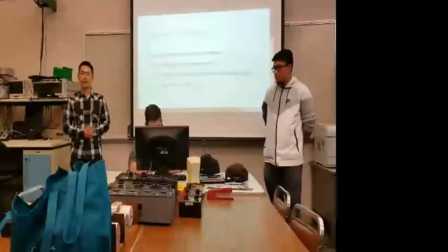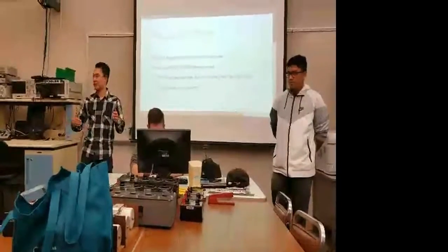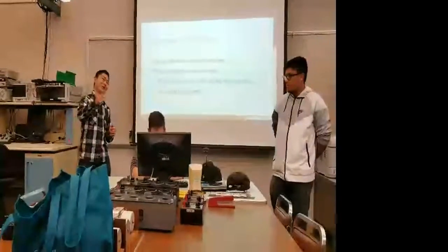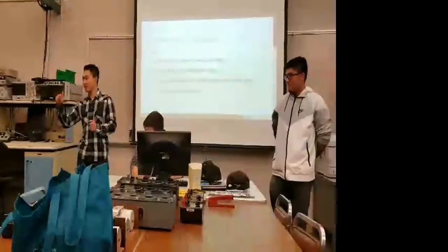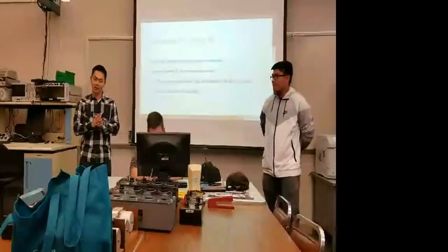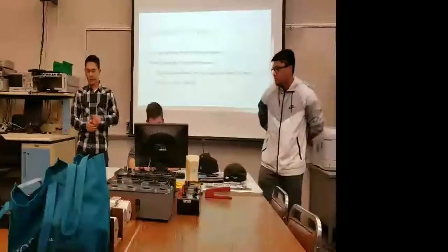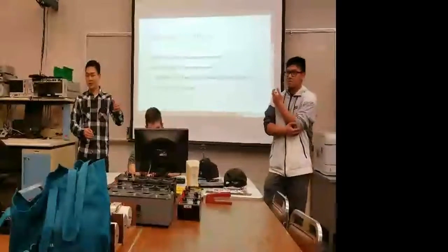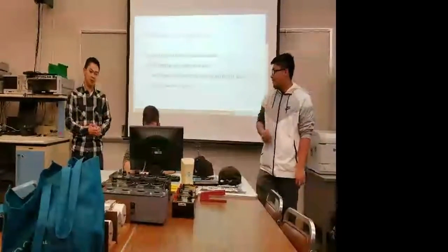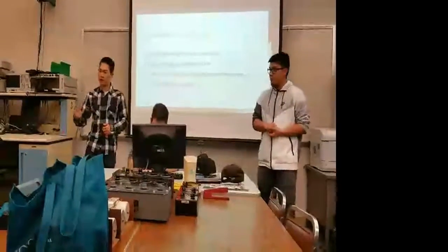The component that gave us the most trouble and pretty much set the standard for getting by was the antenna. Ideally we're supposed to operate within the 2.4 to 2.5 gigahertz range, but when we built our antenna, it was actually lower, at 2.35 to 2.365 gigahertz. So that pretty much said, all right, this is where all your components are going to need to be. Following that, our getting by, which was not really getting by either, was the amplifier, which pretty much halted the building of our system because our amplifiers were not giving out enough output.